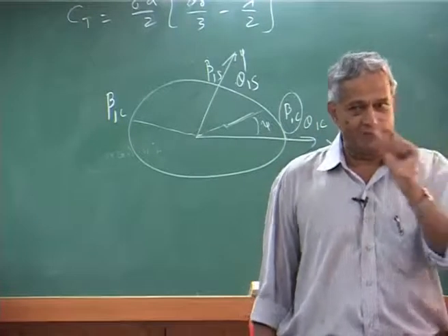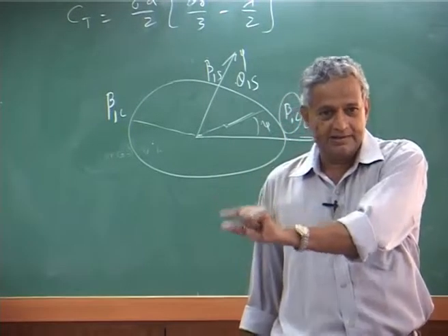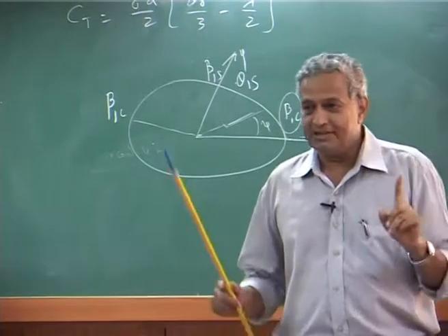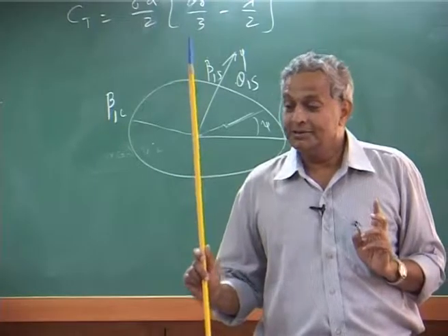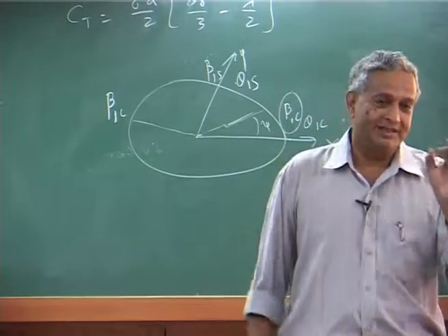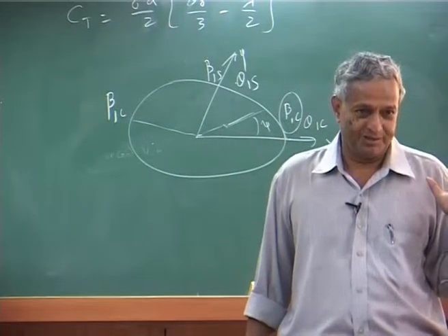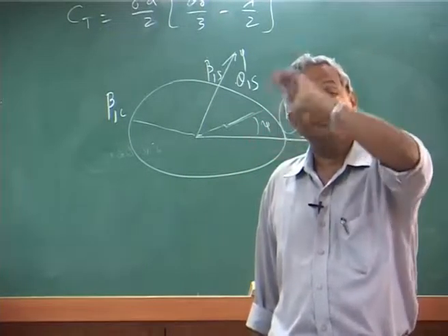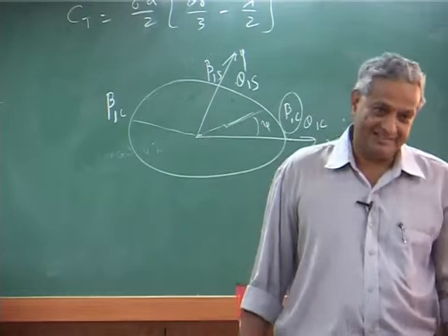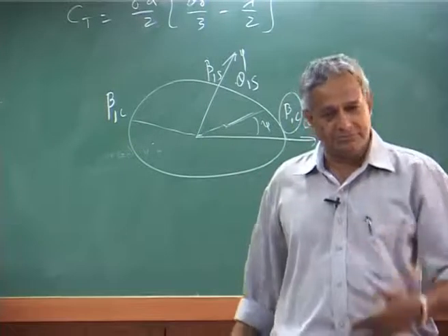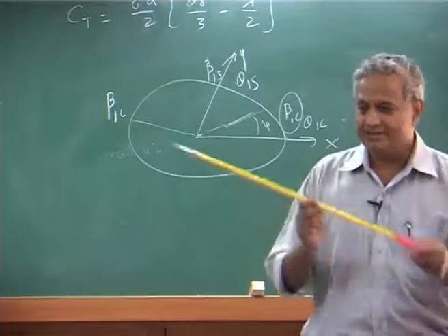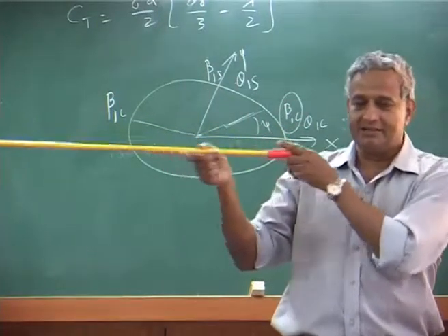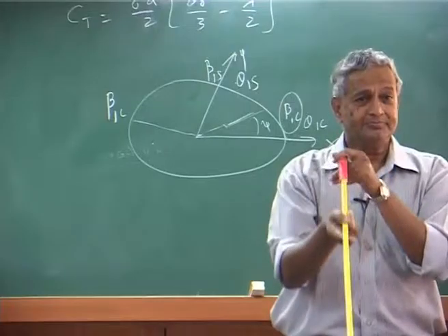That means, when the input frequency is equal to the natural frequency, the phase difference between input and output is 90 degree. That means, if you give an input now, the effect will be shown after 90 degree, then you convert into time. Here we know that 90 degree is basically, in this disc, if I change my pitch angle here, the response will be here.